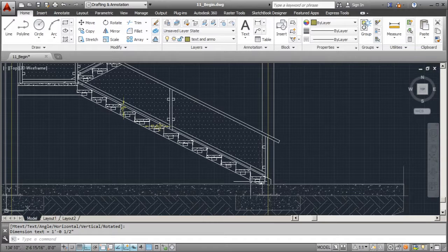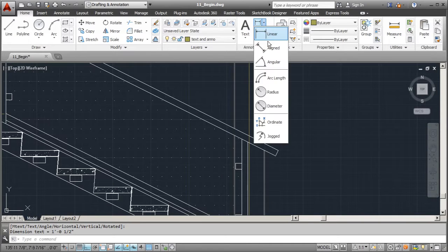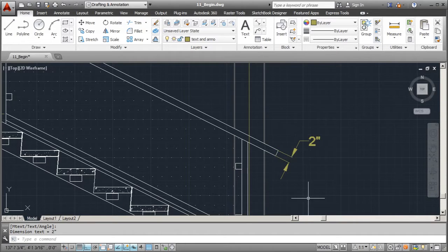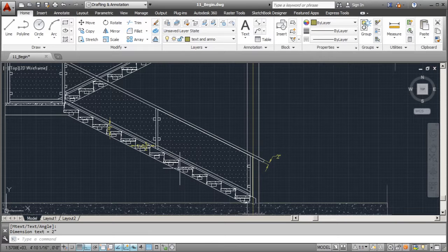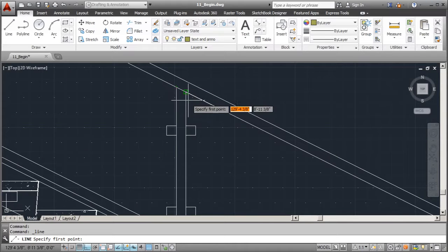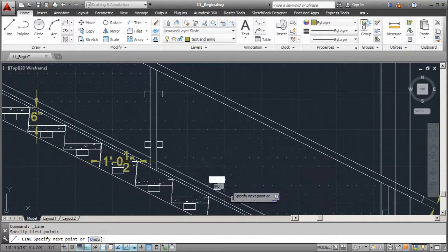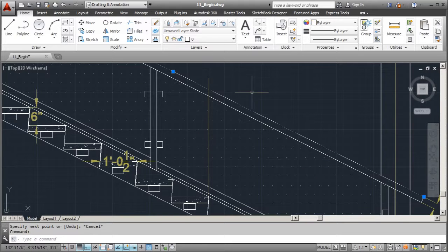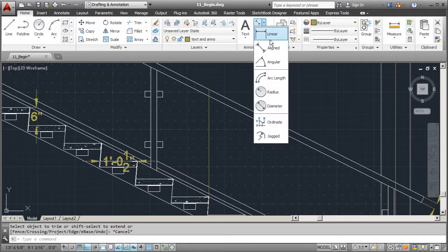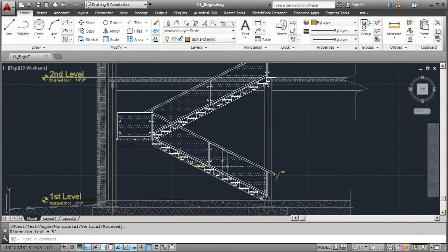We need to get the thickness of our rail. Make sure it's graspable according to code standards. I need to get the height of this rail system as well. So I'm going to draw the line because it's going to be really hard to get the dimension on this angle here. So I'm going to go from my nose here to there. I'm simply going to trim that end piece off. And then we'll add that dimension. So from here to there should be 3 feet, like so.